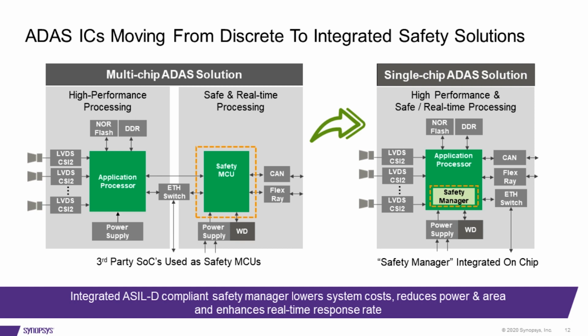But as with almost any part of the semiconductor industry, in order to reduce power and area and all those sorts of things, more and more of the functions are being integrated onto the SoC, and this is true with safety as well. What we're seeing is that in order to keep what's required for isolation between the functional aspects of an SoC and the safety-related aspects, many architectures are moving toward having a dedicated processor on board that manages all the safety escalations for the entire SoC.